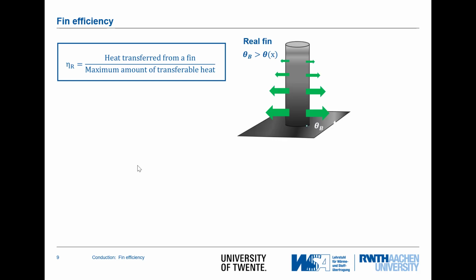So for a real fin, we see that the temperature here at the bottom is higher than the temperature at the tip, and as such, more heat is released over the surface here on the bottom and less heat is released on the top part.